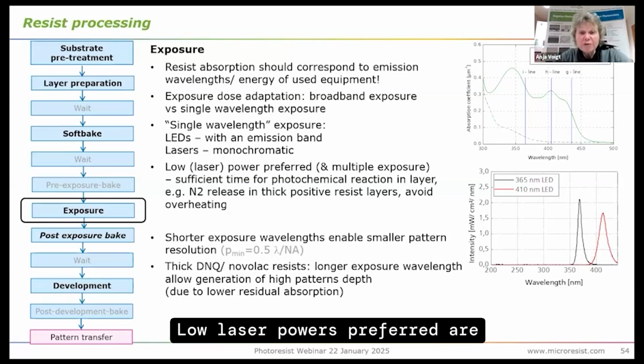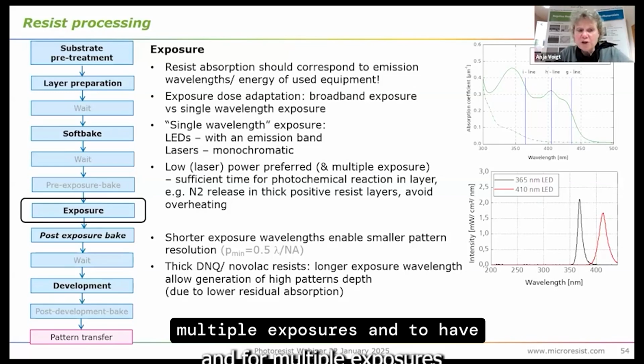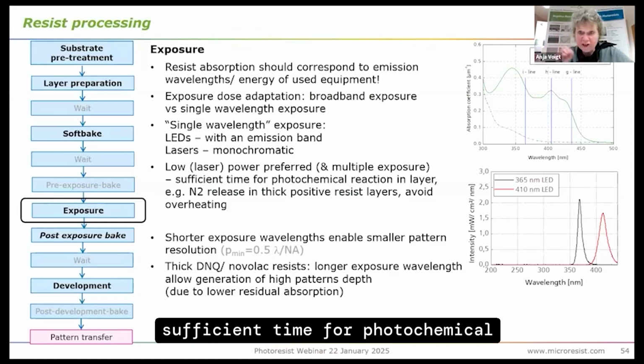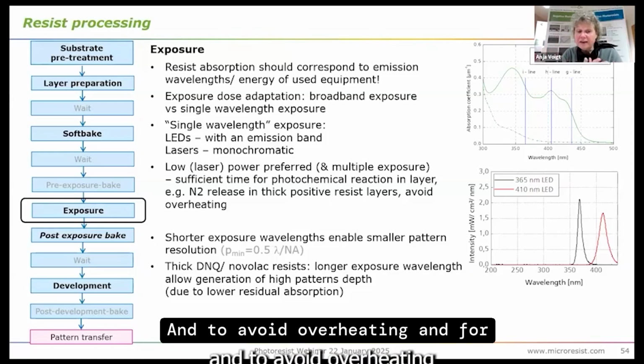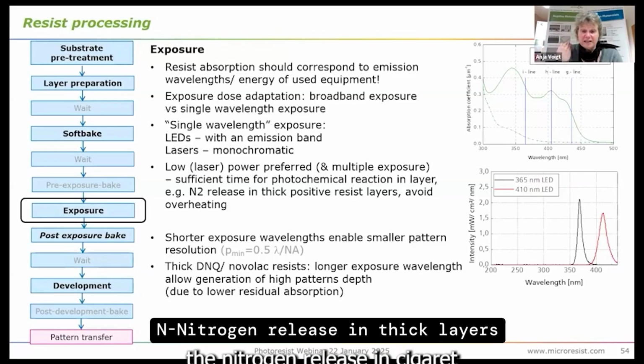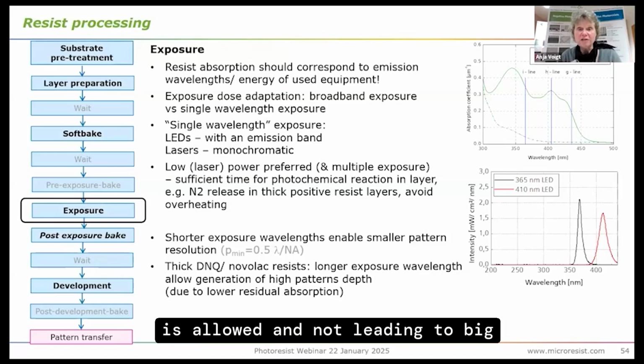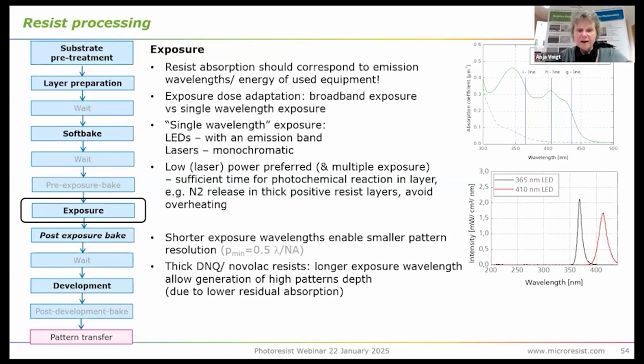Low laser power is preferred, or multiple exposures, to have sufficient time for the photochemical reaction in the layer, to avoid overheating, and for the positive resist so that the nitrogen release in thick layers is allowed and does not lead to big bubbles.